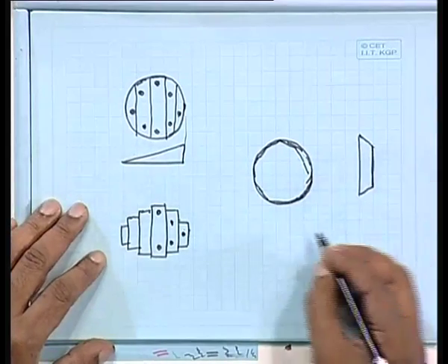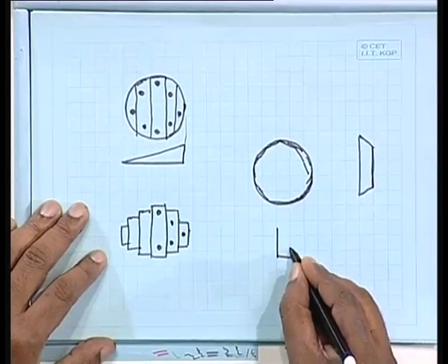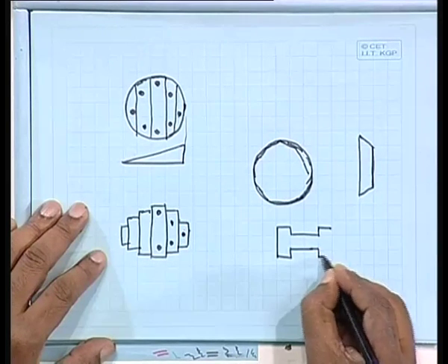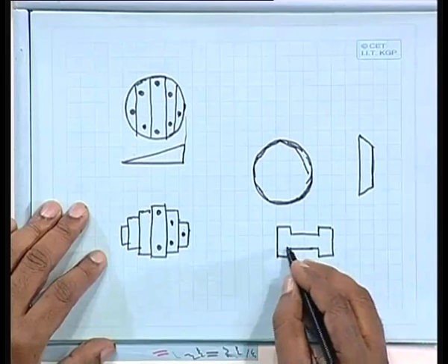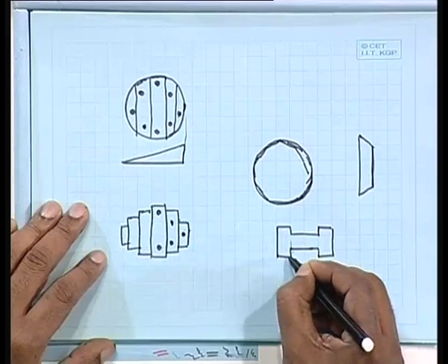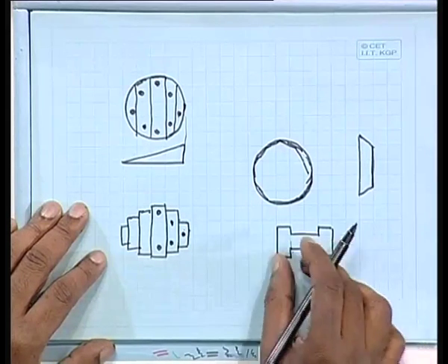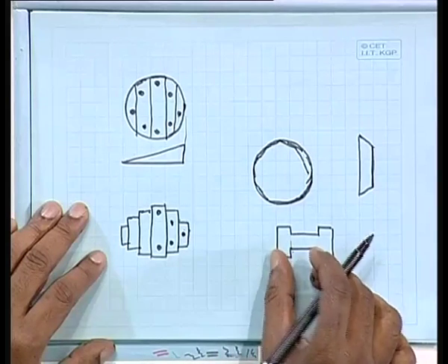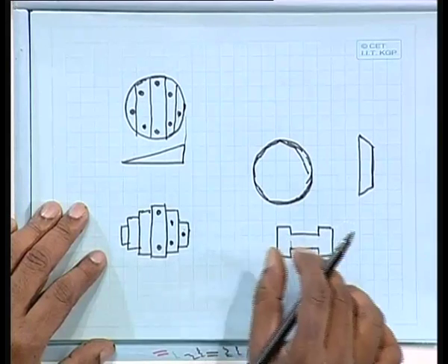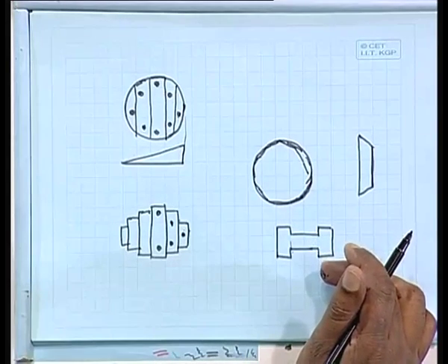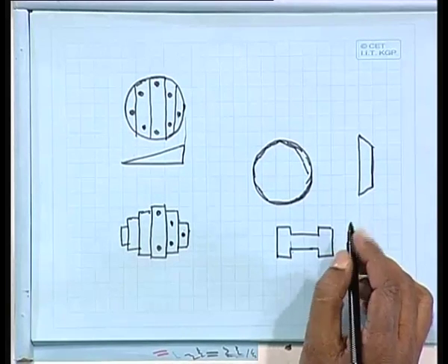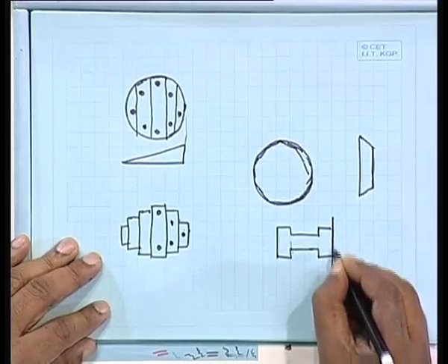Not only that, you can take a section say like this, the column is like this. Which is nothing but 3 rectangulars. So I can take this one, this is another one, this is another one, 3 rectangulars, and each of them are stressed at different levels. This one at highly stressed level, this one in the middle, this one at the end. So for each of them you have to find out what is the moment capacity and what is the axial load capacity. The moment capacity always we take with respect to this line.